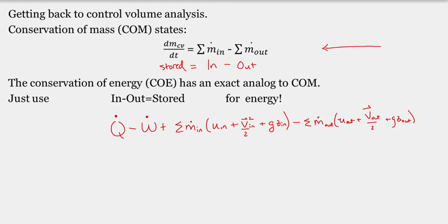Now, so these are my ins and outs, right? I've now identified all the different ways that energy can be transferred into and out of an arbitrary control surface or control volume. And we also need to allow the system to potentially accumulate energy. So we're going to represent that term just like we did up here for the conservation of mass, as an unsteady control volume term. And that energy within the control volume is an uppercase E, so we know that that is an extensive property.